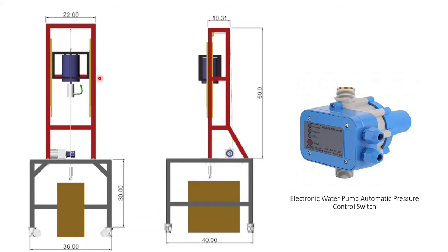Our pressure loss computations account for change in area going from the hose into the swivel and down the drill string. Additional pressure loss computations are made within the drill string all the way to the BHA. Pressure drop across the bit is computed based on published formulas, assuming we have two nozzles. Annular pressure losses are computed across the BHA and across the drill string. Prior to the annular pressure loss calculations, using an assumed ROP of 1 foot per hour, we estimate the volume of cuttings and correct the mud weight.